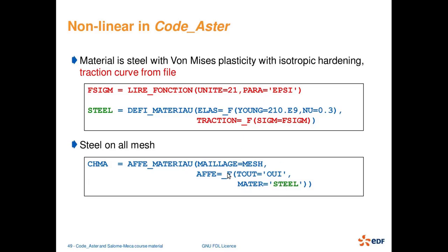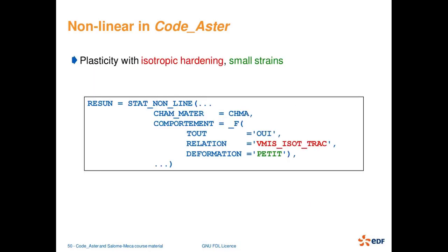So this is also possible, but for soil it is not so useful, because you know that the stress-strain curve of a soil depends on many factors like pore pressure, confining pressure, relative density, then type of soil. So we have to use appropriate constitutive relationships for soil. Those we'll discuss a little later.